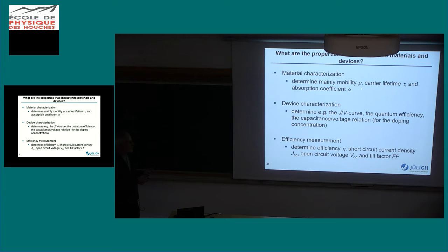So if you have a high absorption coefficient, so a large interaction of light with your electron hole system, always talking about the useful absorption, that makes these electron hole pairs, if this is high, carrier lifetime in the radiative limit will be relatively low. So there is a limit for that one.